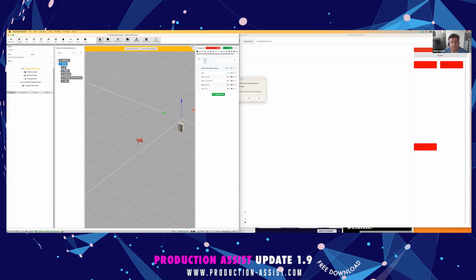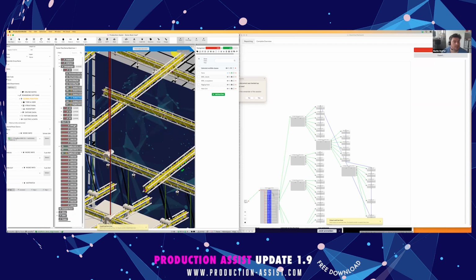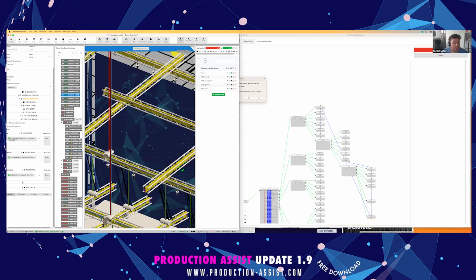So for example, if you want this fixture to have an additional network interface, you just click in here a new object, add an electrical geometry, and define it then as a network input and output, which, for example, can use an RJ45. If you then save and close this definition, you see that all fixtures automatically now have this connection in here inside its option.